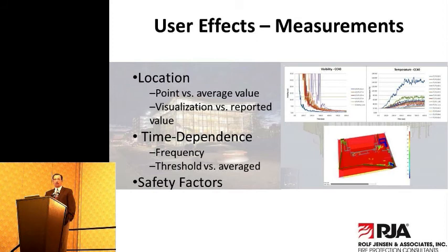From the measurement side of the house, as Craig said, we're taking a look at, from the performance-based design standpoint, temperatures, soot concentrations, and species concentrations at specific points in time and at specific levels throughout the atrium in this very convoluted space. So one thing we have to take a look at was how we're going to view them, and obviously simple graphs are effective. We did use the companion software program SmokeView to take a look at the results as well. So we did look at slice files, we looked at ISO surfaces.